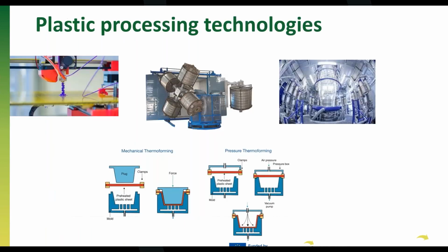I already start to focus on the different technologies that we have. I will go more deeply into injection molding, but keep in mind that we have some other technologies: 3D printing, rotomolding, film blowing, thermoforming. And in most of them, the key parameters that I have mentioned, in terms of temperature, Tg and melting point, and in terms of rheology, the viscosity of the material, are key for the processing of these polymers and to obtain a good product.